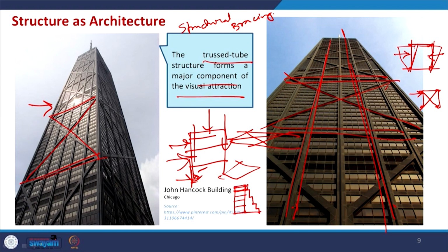The load here will be just the load of the column of the upper floor, but if you calculate this, that means the addition of all these floors to this. That is why you can see the load transferred to the ground is quite huge, and it is like a stepped diagram. So, for high rise buildings also we have to take care of that.